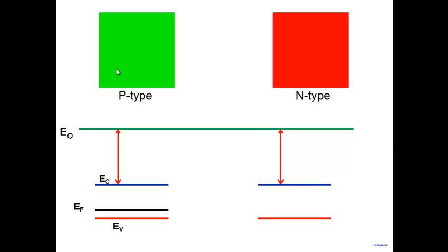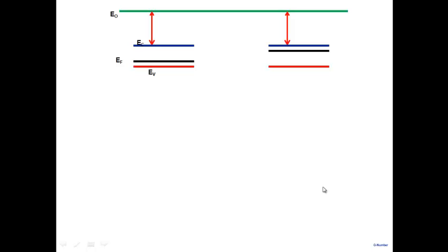Electron affinity, we are talking about both regions being the same silicon. Electron affinity is the same, and then this is n-type, so Fermi energy is here. And from the doping, we can determine what the place of Fermi energy is. All right, so that's before equilibrium. After equilibrium, we know what will happen when we bring them into contact. This Fermi energy is higher than here.